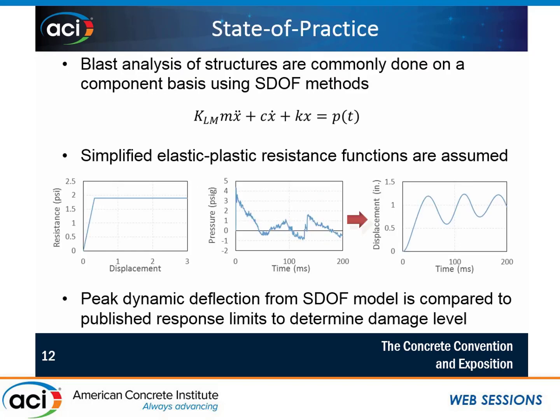Moving into modeling, really what you're doing when you're solving or calculating what kind of damage you're going to have to a blast-loaded component, in most cases you're going to be using a single degree of freedom method. So you're solving the equation of motion, and what you really ultimately need is the Kx, and then this becomes really a nonlinear term rather than just Kx. And that's your resistance function down here.